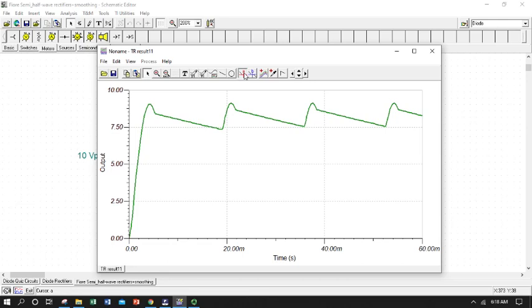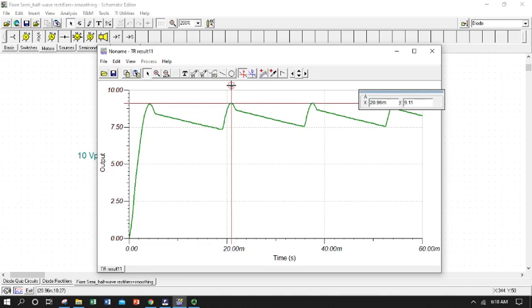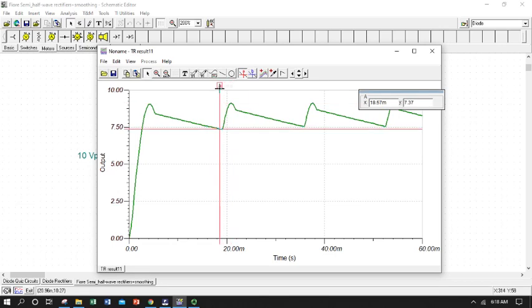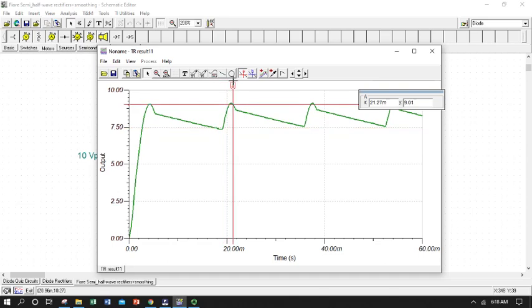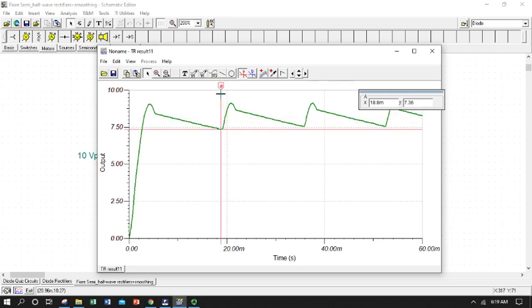So just to show, try to point this out here. The difference between our peak and this little valley, this low point in the RC discharge, this is our ripple. So this is the variation in voltage that our resistor is seeing. And either the bottom or somewhere midway there would be considered our true DC level, so the average time invariant signal that we're getting.